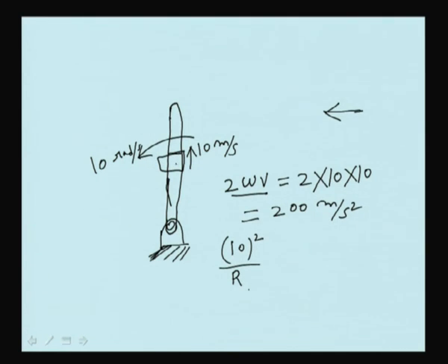So this component decreases as the particle moves. In this problem, the Coriolis acceleration will have the same direction as the tangential acceleration.